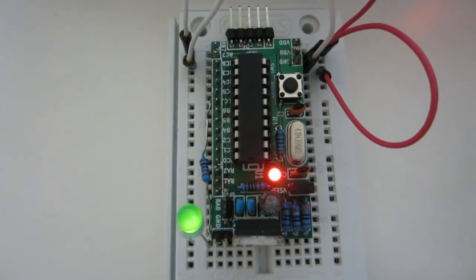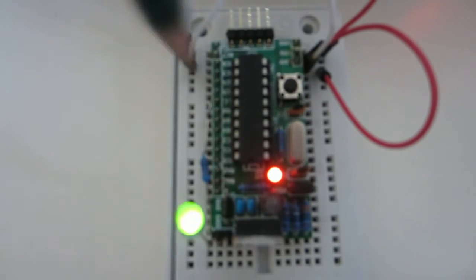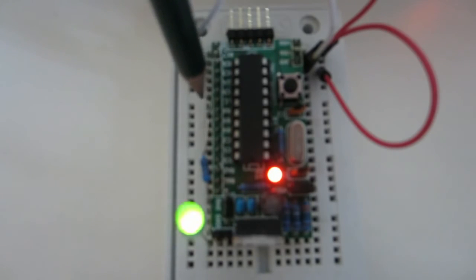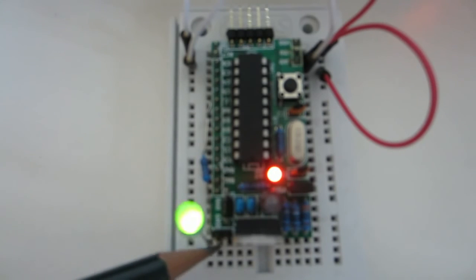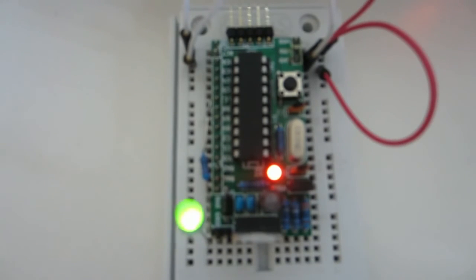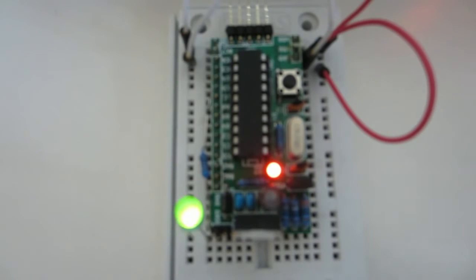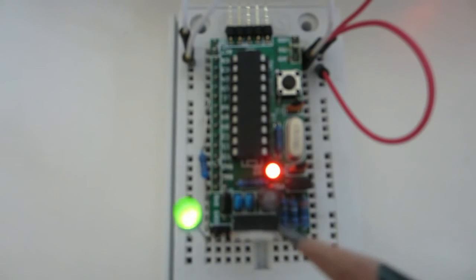So this is the example application. We can see our PIC microcontroller right here, and we've got the PWM pin connected to a resistor, and the resistor is connected to the anode of an LED here, and the LED's cathode is connected to ground. And as you can see, as we've seen in the example code, the LED actually fades up, and if we were to make the PWM much slower, then we could actually see that the LED is not actually getting brighter, but it's just switched on and off all the time.